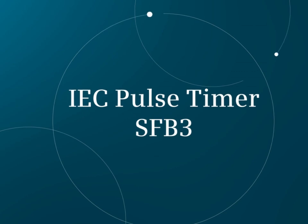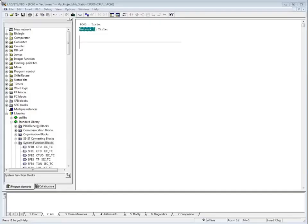Here you will see how to use the IEC pulse timer SFB3. We will do our programming in FC60. FC60 has already been called from OB1. The IEC timers are located in the Standard Library System Function Blocks folder. Drag the pulse timer SFB3 to Network 1.